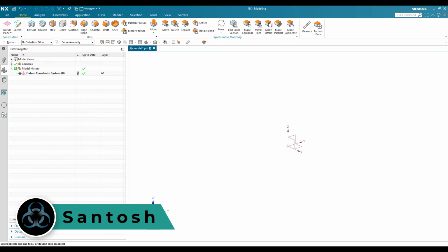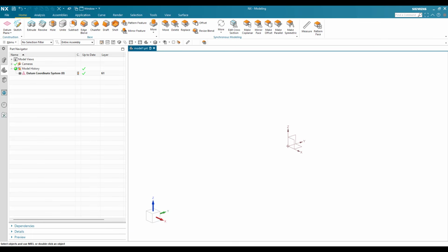In this video, I'm going to give you complete knowledge on the Sketcher environment in the NX19 version. I have divided this video into three parts. The first part is going to be creating curves and lines, and the second part is going to be giving dimensions for the lines whatever you have created. And then the third part is very important, that is giving a constraint, a geometric constraint, to particular curves. So by the end of this video, you will be able to create simple sketches in NX19 or lower versions.